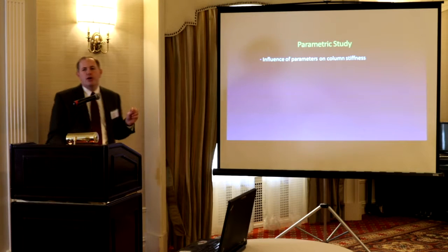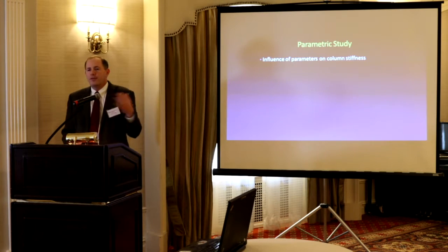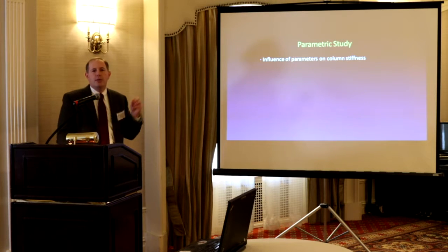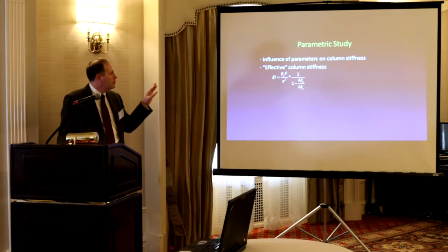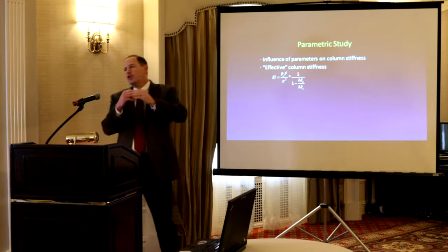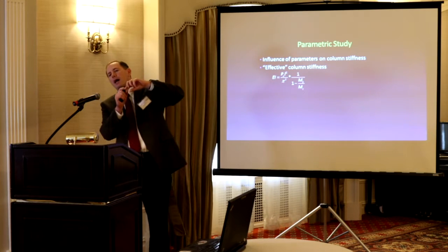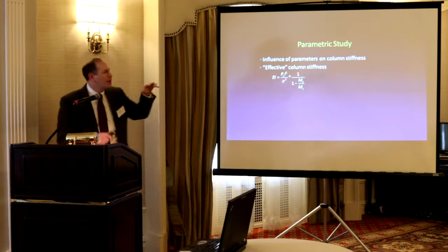Now, what we wanted to do, though, I mean, we could do that and write a software package. You could do that yourself. We don't have to write the package. You could just analyze it. But we want to look if we could come up with something that would be a code expression a little simpler. So we looked at the influence of all the parameters on stiffness, and we wanted to come up with an effective stiffness. Realize the variation of cracking is different everywhere throughout that column, so we need to come up with one common EI that represents the entire column, and that's the challenge.